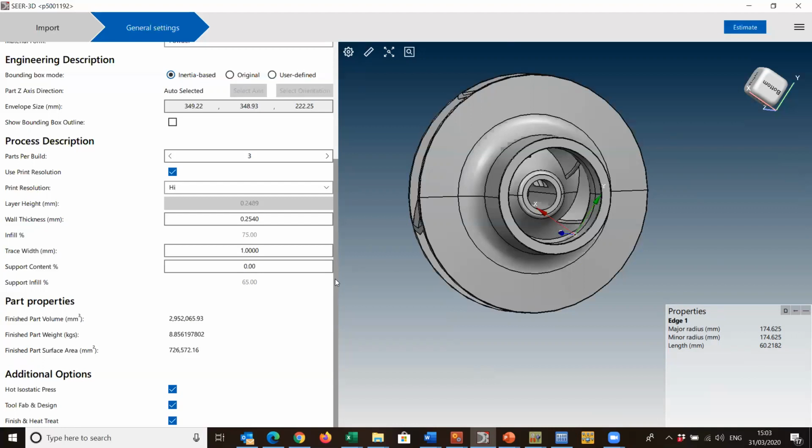These will contain things like the tooling list. So what tools are required to produce this? What are the finish and heat treatment operations you may wish to have as default for a part of this type? It may be a sanding operation, it may be a blasting operation, it may be a painting operation, treatments, whatever it may be, you can do that also. So these are contained and controlled in the environments, in the knowledge bases, and I'll leave them on so that when we run the model, we can see the resultant estimate and what is brought in automatically on our behalf.